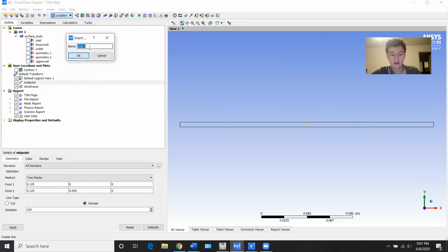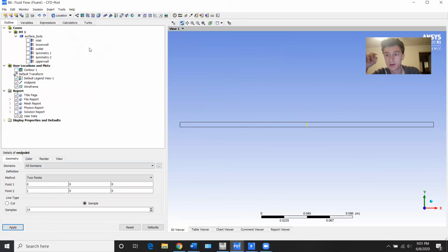Now we'll add another line, endpoint. For here, you can add 250 millimeters, but I'm going to make it just slightly less because if you make it all the way at the end on your chart, sometimes it gets a little weird just because it's at the limit. So if you make it just approaching the limit, like a little bit less than the endpoint, you'll get a smooth curve. Otherwise, there might be like a little something weird at some of the endpoints.